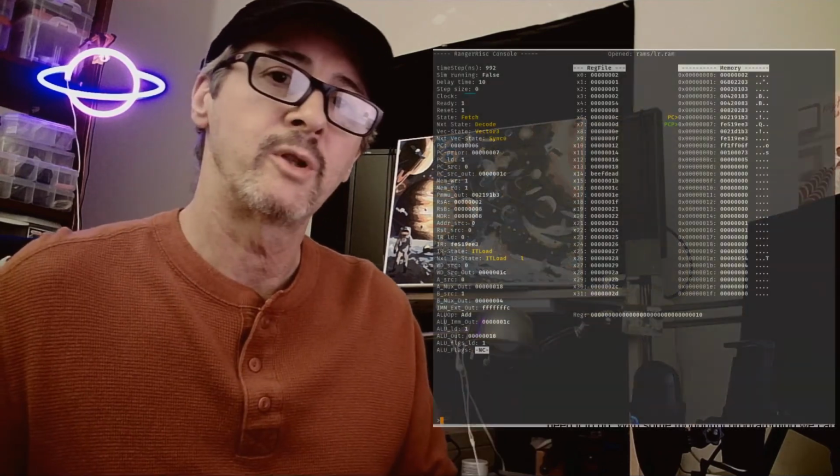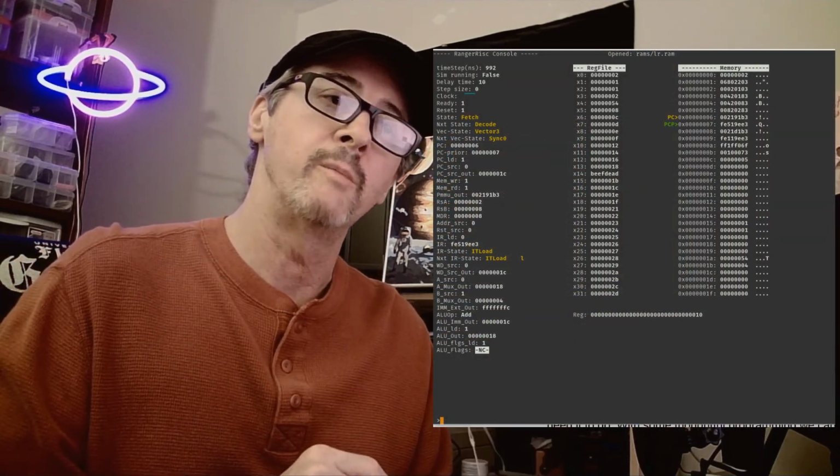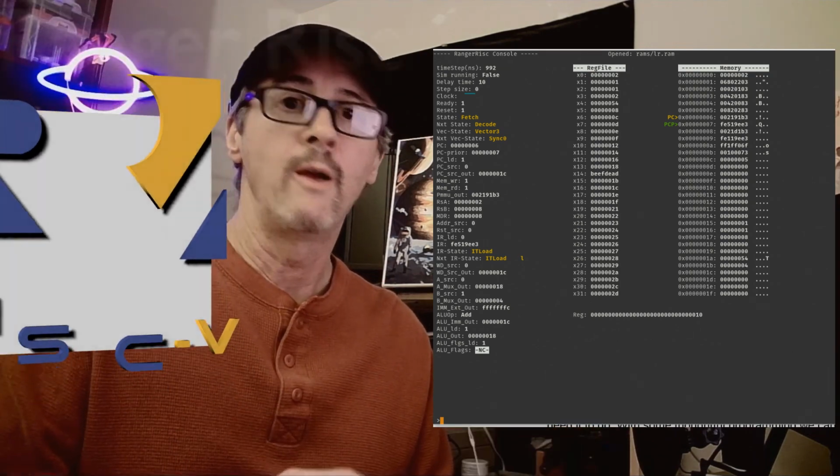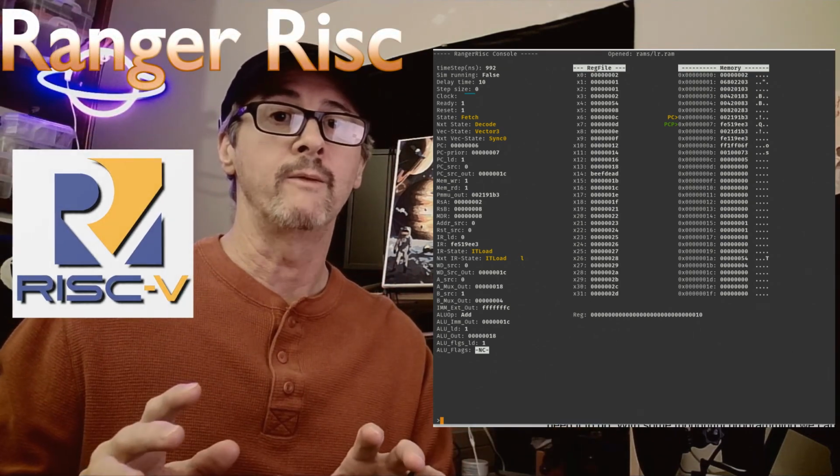Awesome. We just implemented the CSR instructions and the MRET instructions and created a bunch of machine code to run them through their paces. However, as we saw in GTKWave, it can be quite difficult to see the action through the forest of signals. So in the next episode, we'll update our ncurses simulation to include what we need in order to see our programs from an entirely different perspective.